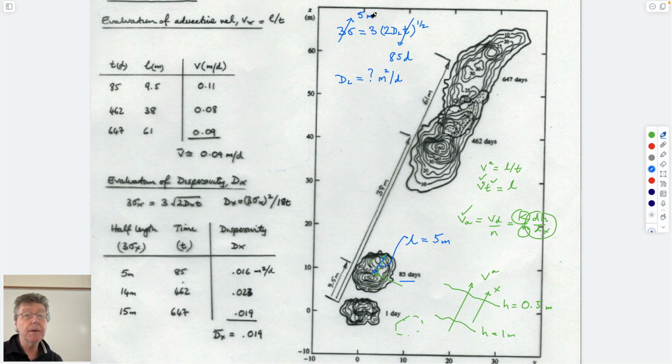It's certainly dimensionally homogeneous, this equation. So you just have to be consistent in your units of length and time. And so if you do that, you don't need to solve that complex Gaussian probability distribution function. You just need to know this one outcome from it to calculate the longitudinal dispersion.